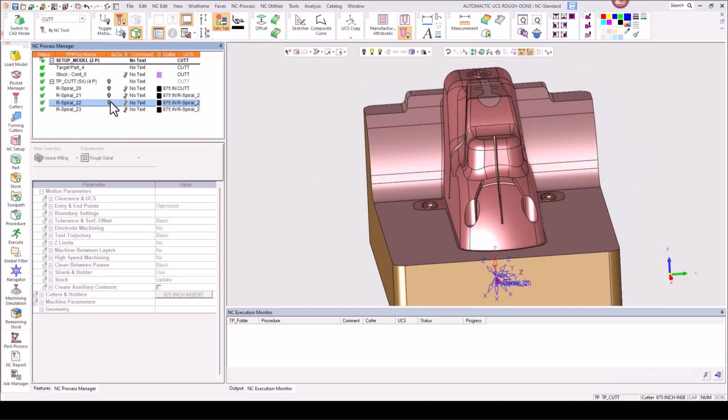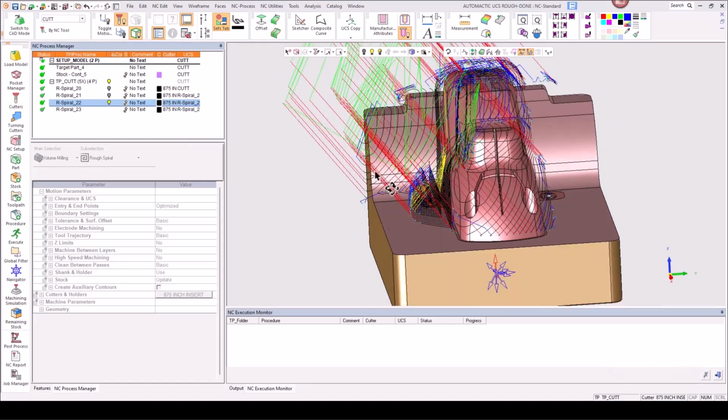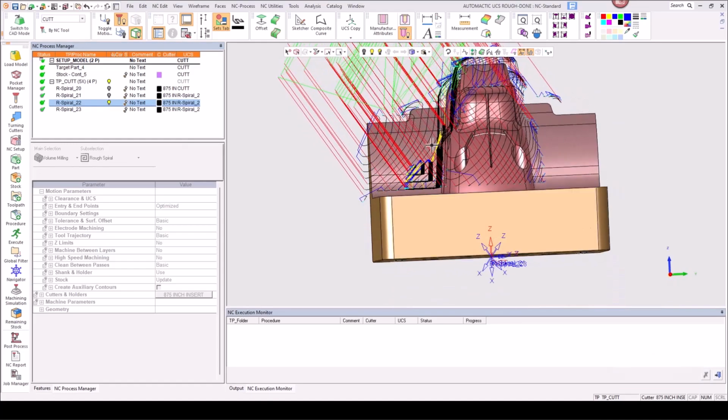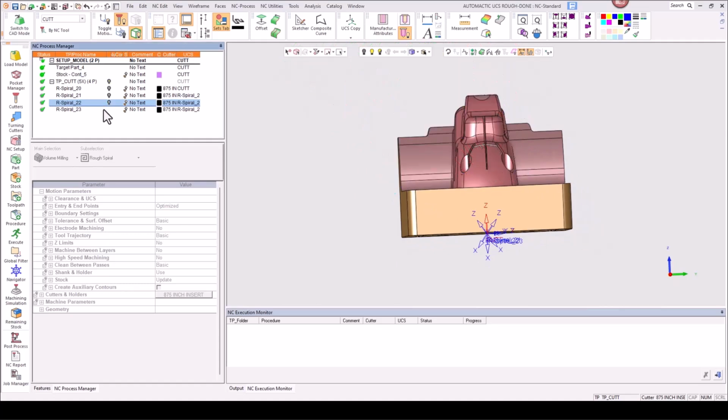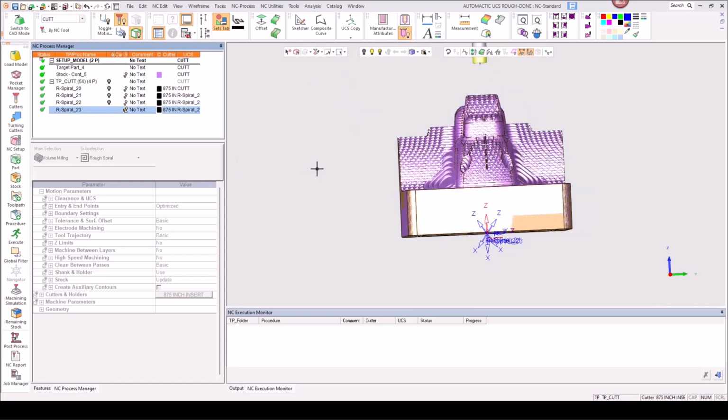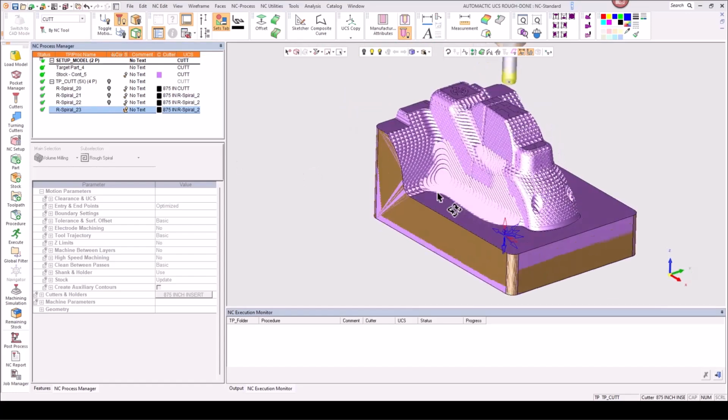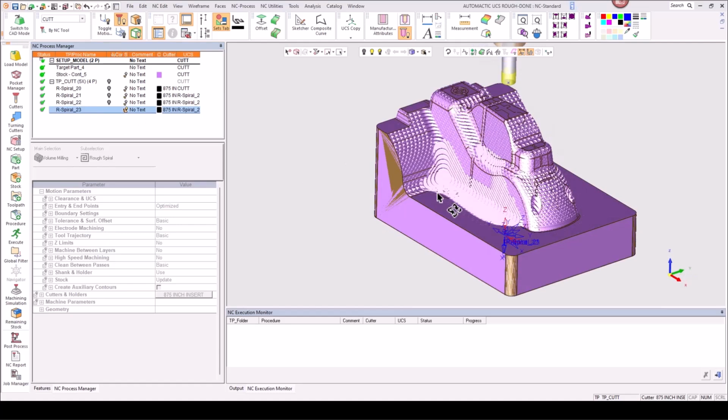So at the angle resolution we put in, 45 degrees, it was able to find this side needed removal and this side needed removal. And then when it got to the last solution, it said, hey, there's no reason to calculate based on the input given. So there's still stock here, but based on the 45 increment that I gave it with a max tilt of 90, it said there's no more here to do.